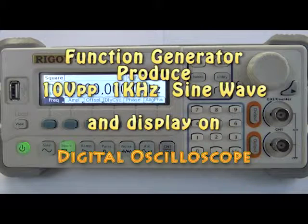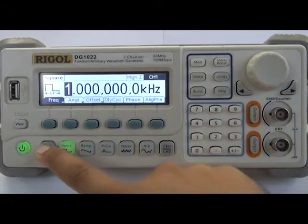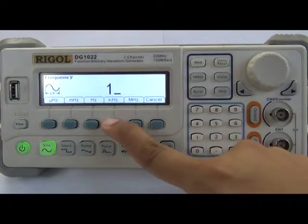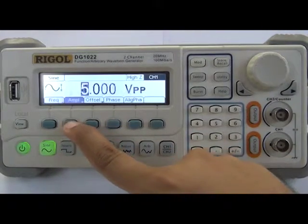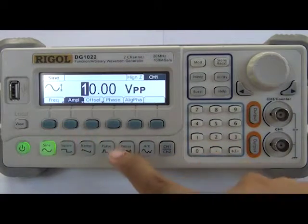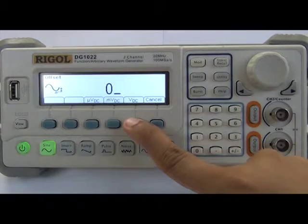Now we have to display a waveform on the oscilloscope. We have to set up the function generator to produce a 10 volts peak-to-peak 1 kHz sine wave. But first, we have to change it to sine wave. Change the frequency to 1 kHz. While the amplitude, change it to 10 volts peak-to-peak. Remember to change the offset back to 0 volts DC.